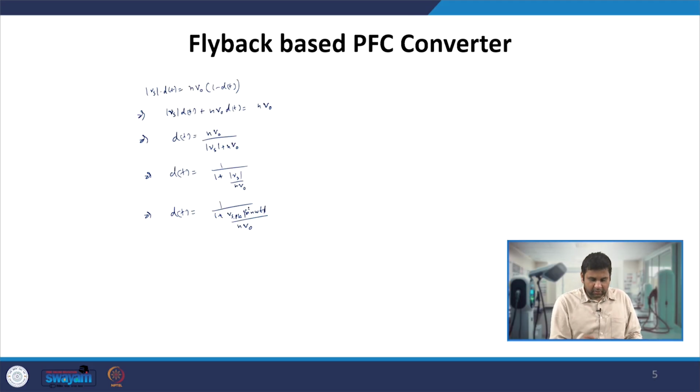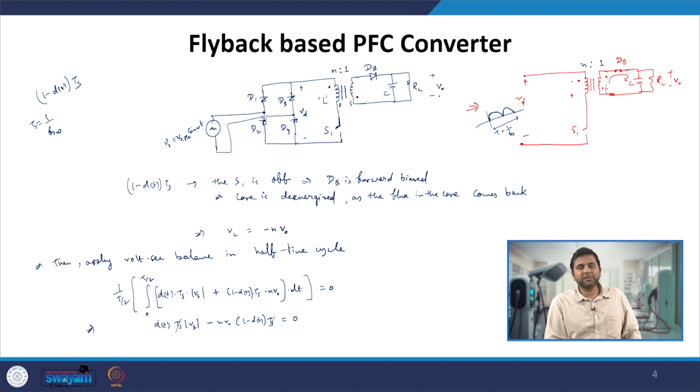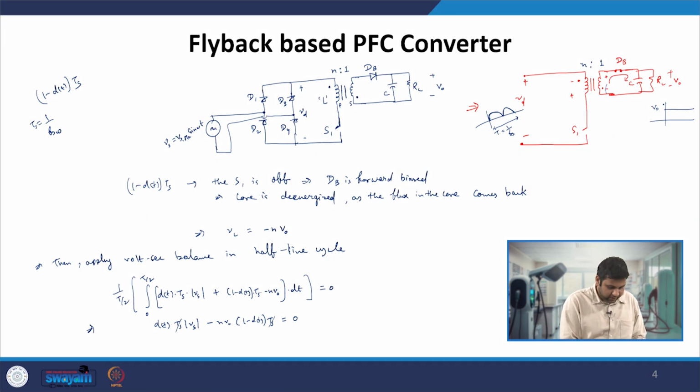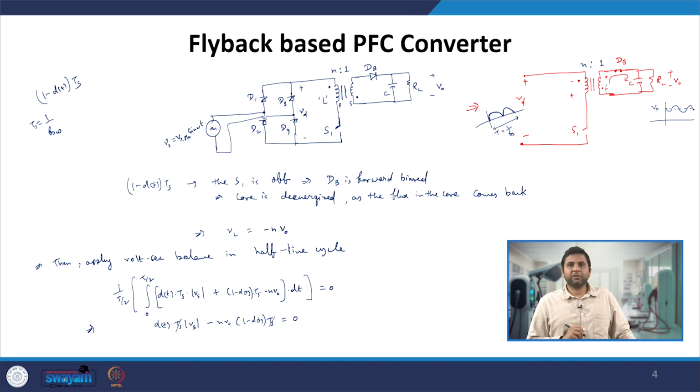then only we can ensure that the output voltage is a constant DC voltage, as here at the input we have the rectified DC and at the output we are getting pure DC, which is nothing but equal to V naught. Obviously, over this, if we draw, we have this V naught, over which we have the second line harmonic voltage coming like this. I mean we have the second line harmonic ripple riding over the capacitor.